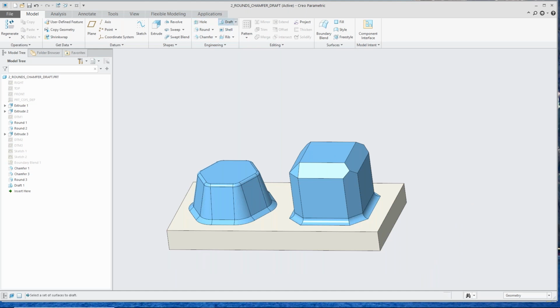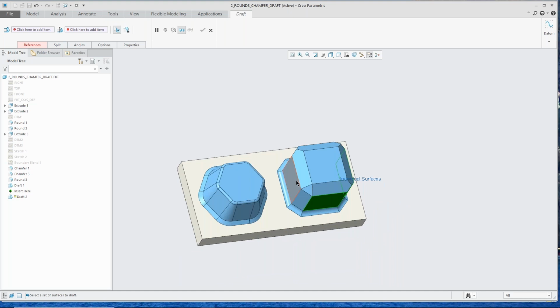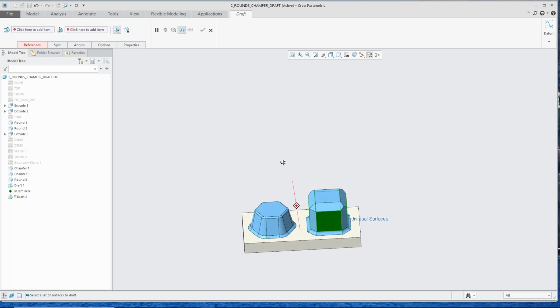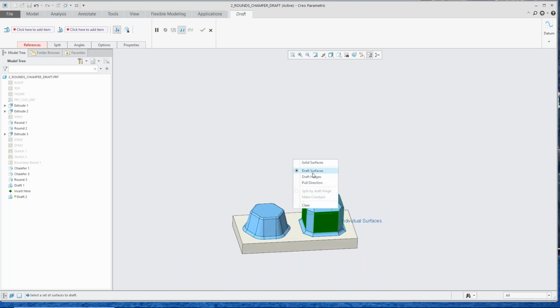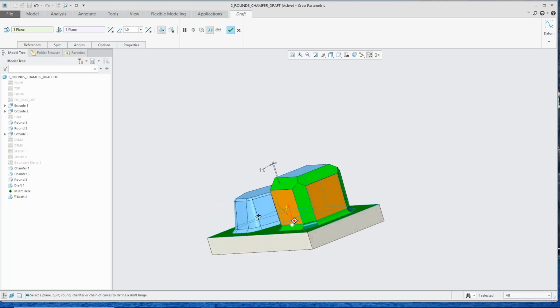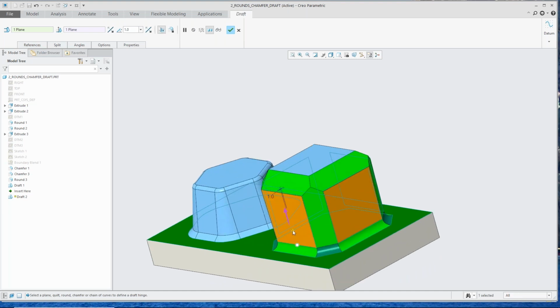Again, this one, I just use chamfers, but I use different types of manipulations in the chamfers. Let's pick these guys. We'll pick them as our draft surfaces. Again, our hinge, this time we'll maybe pick the bottom. But again, as I drag this, even though we have kind of different transitions in the chamfers in this case, or it could be rounds, it doesn't matter because all it does, in the background, is pull them off, put in the new geometry, and then put them back on.